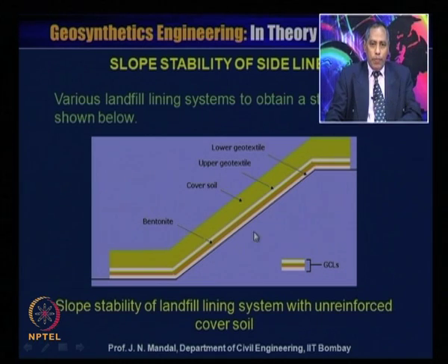You can see here the slope, and this is the geosynthetic clay liner, which consists of a lower geotextile and this bentonite, and then upper geotextile, and then you are providing the cover soil.